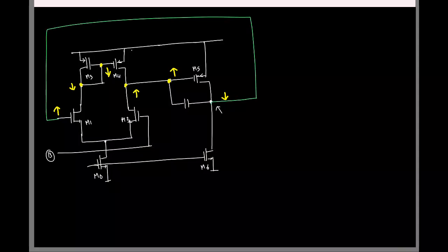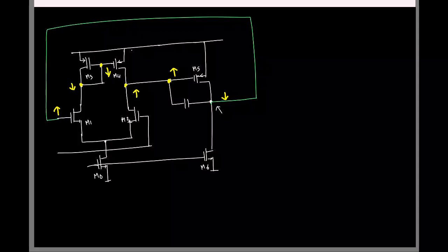Okay. And at the other terminal, I'll apply the common mode, which we saw will be roughly at VDD by 2. So this will be set to VDD by 2 ideally. And we saw this will be equal to VDD by 2 if we make sure these two potentials are equal, right? We saw that if these two are equal, there will be no offset between these two, else there could be a systematic offset.